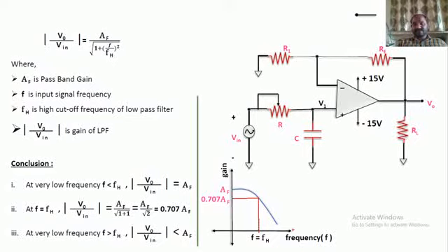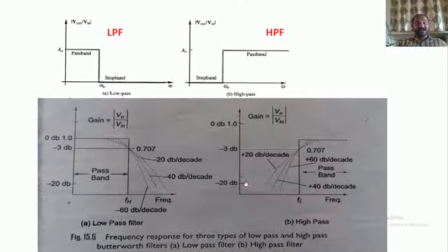We are seeing these values in terms of normal decimal values, that is, fractional values. But some of the textbooks explain this in terms of the decibel graph. Okay, in terms of the decibel. The other way of explanation is at what point the gain... So here I am assuming that V0 by Vin equals 1. The gain AF equals 1. Means this is the AF value. AF equals how much? AF equals 1.